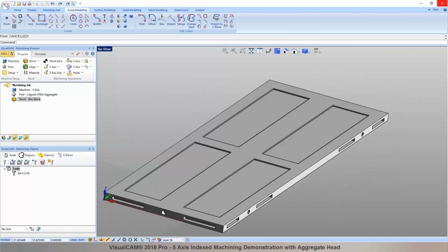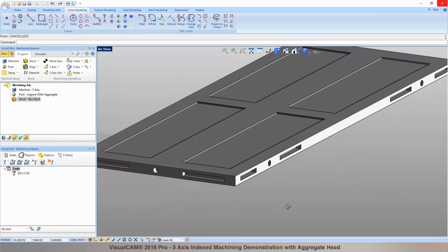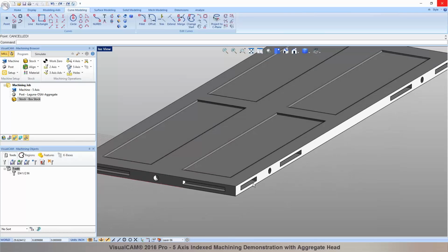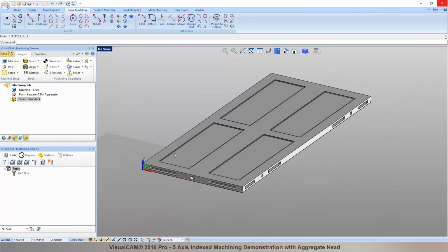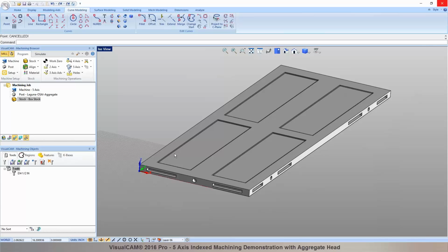Now, if you're going to be programming by orienting the tool axis, locking into this plane and programming it, we call that indexed or positional 3+2 or 5-axis index machining. So basically we are locking the tool axis to a given orientation and then programming it. To do that in our CAM product, in our Pro configuration, we have a module called 3+2, which allows us to create additional coordinates to program it.